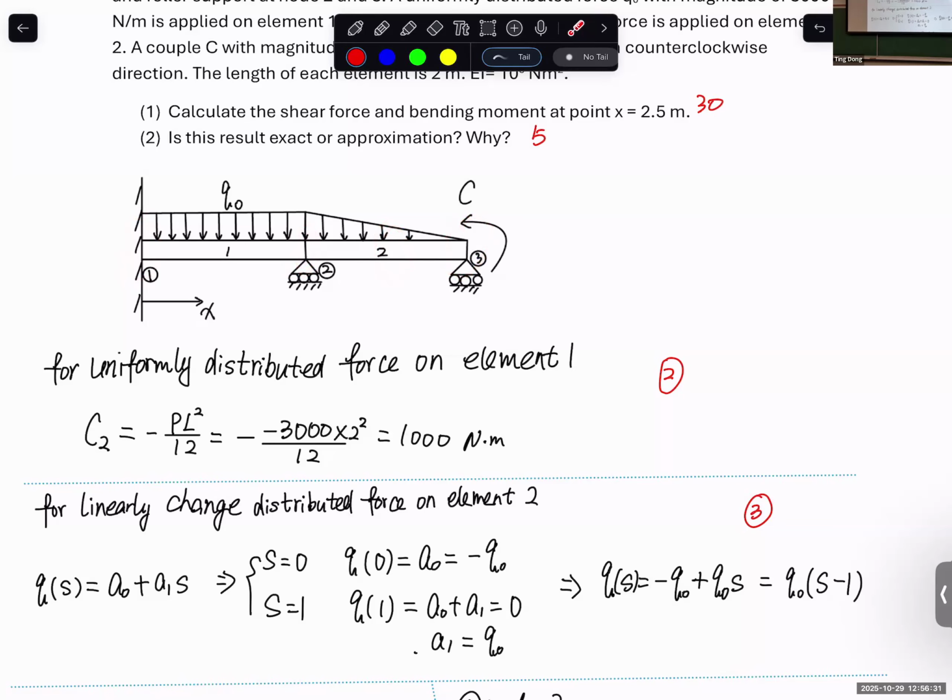That's why I keep emphasizing that as an engineer, we need to know what we want to solve, what are the necessary information to get that final answer. And we know that for solving this one, we don't need the equivalent force and couple here. And also for the equivalent force here, we don't need it. And equivalent force here, we don't need it. We only need 2 components for the first force vector. That is the corresponding couple here and a corresponding couple here.